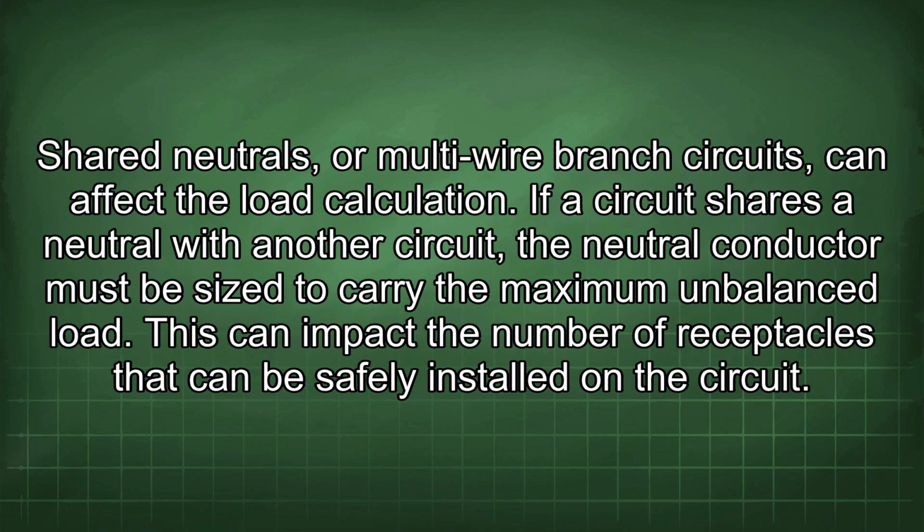Shared neutrals, or multi-wire branch circuits, can affect the load calculation. If a circuit shares a neutral with another circuit, the neutral conductor must be sized to carry the maximum unbalanced load. This can impact the number of receptacles that can be safely installed on the circuit.